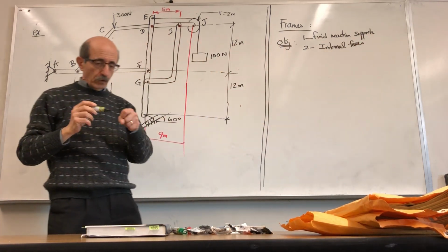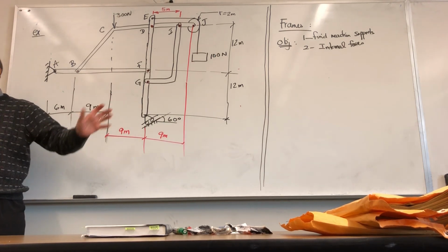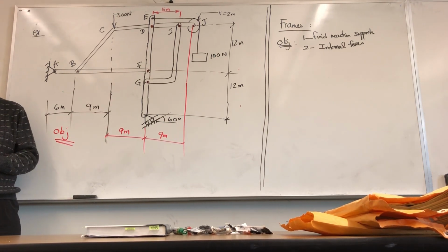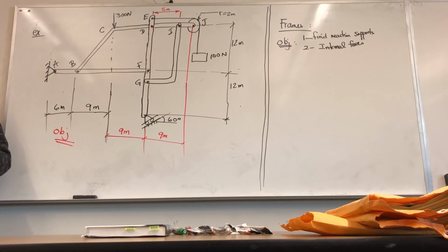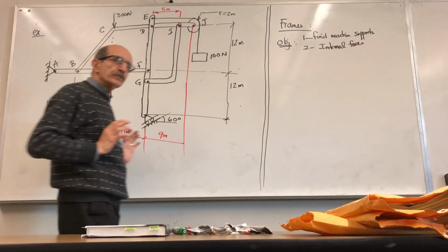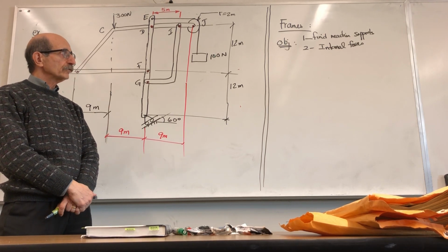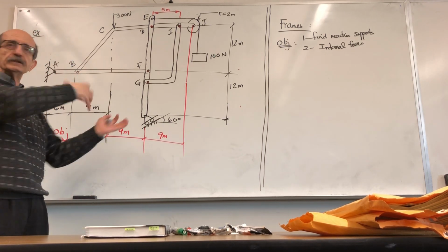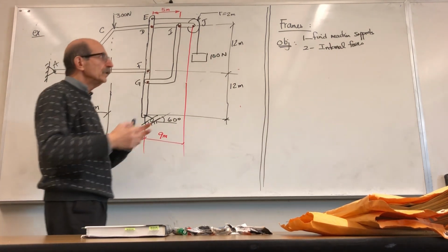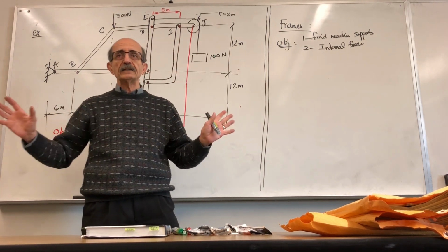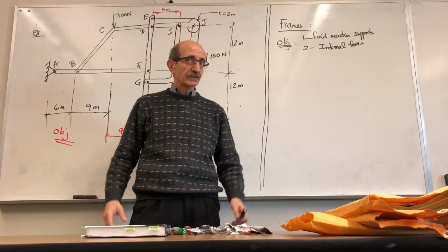This is what I want to basically go over to set a sort of a methodical and organized way to do these problems. I don't expect you to memorize them, because after a while, you really get the habit of using that approach to solve frame problems. Solving for the internal forces is not something that you just jump into. You have to follow a certain process, and it builds on the main concept that statics is all about: free body diagram. You remember that 85% of statics?